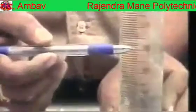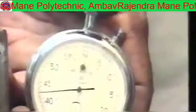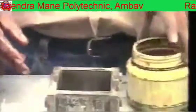Next, the vibrating machine, measuring jar, mixing dish, vise, balance, stopwatch, and mold of 7.06 centimeter size as per IS 4031-1968. Now let us see the procedure of this strength test.